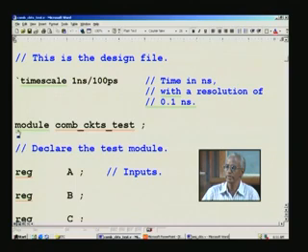So, here you declare module with a space, and then the actual module name, which happens to be the test bench. You give the full name, and notice that .v is not to be given here. If you give .v, I think the compiler will complain.